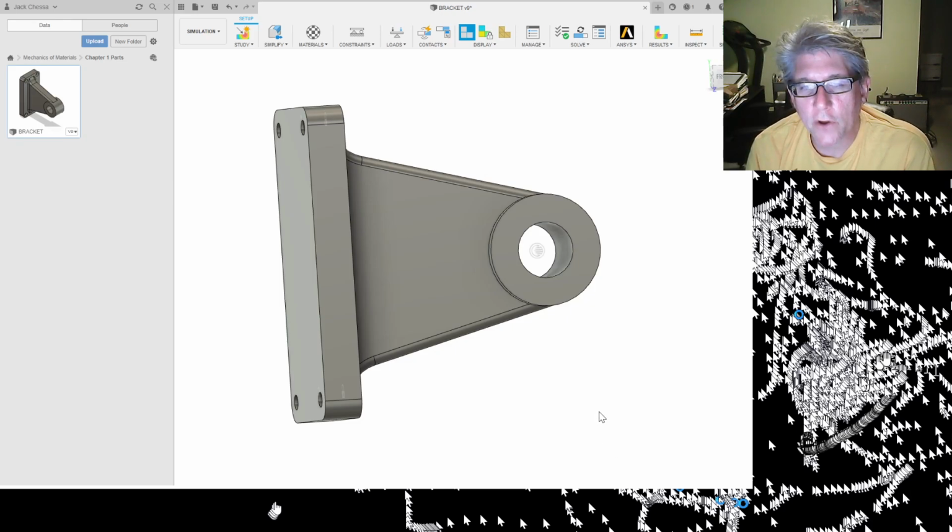Pretty much for these other advanced ones, it's not a bad idea to keep them where they are. Parabolic means they're second-order elements. I know that doesn't mean much to you now, but those are the preferred ones for linear static analysis. Do not change these to linear. Keep those at parabolic. This is on a circle: how many degrees will be spanned by the edge of one element. So, 30 degrees is probably not too bad. The other ones are basically about where it works. So that's not too bad.